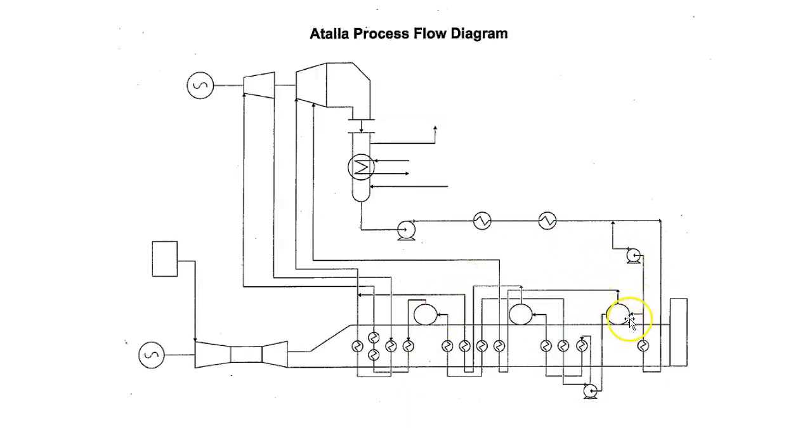The LP drum also acts as a de-aerator, as it's a storage tank. It's usually 6 times the size of these other 2 drums. Also, I failed to mention that the HP drum is usually run at about 1800 PSIG. The IP drum is usually run about 1000 PSIG, and the LP drum is usually at about 80 PSIG. So there's quite a jump between the drums.